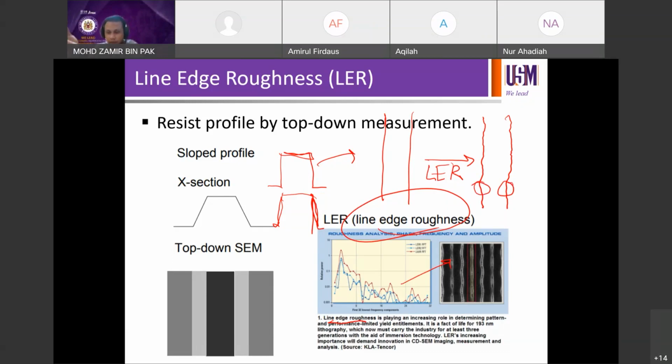You can still tolerate the roughness on the edge because on the side of the profile, because if you're printing 200 and your roughness is like very small, so the noise, signal to noise, and noise is the roughness, is very, very small in comparison to the right, to the intended signal, which is the CD target, 200, 300.